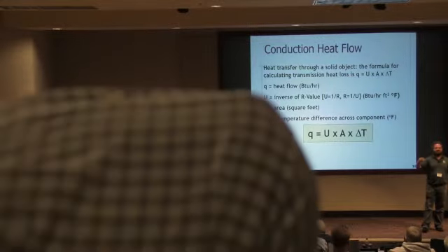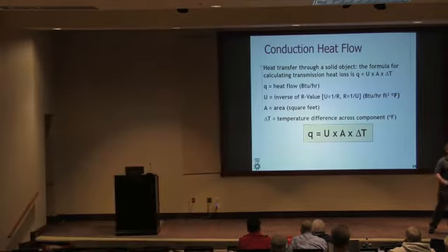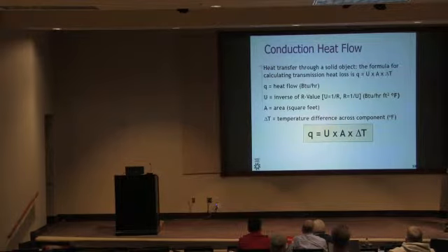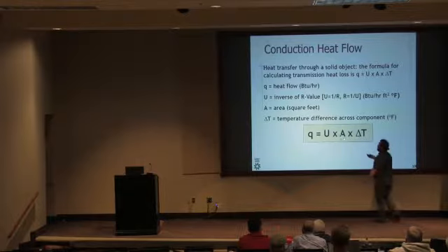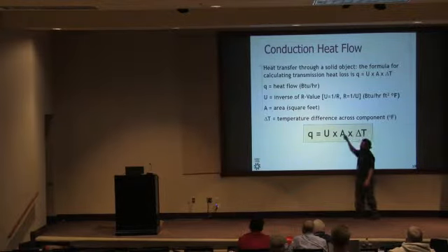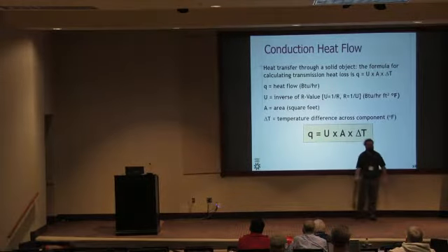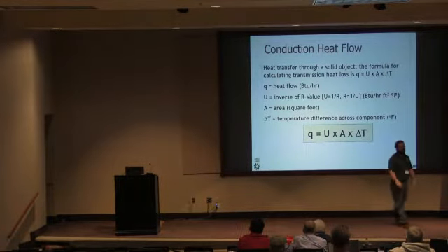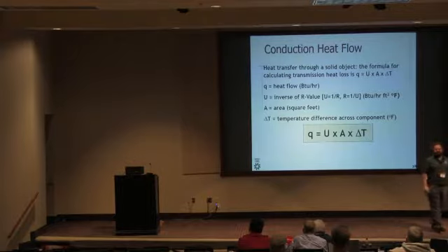It's 70 inside and it's 95 outside. That's a 25 delta T. It's 70 inside and it's 40 outside. That's a 30-degree delta T. How much area, surface area, is experiencing this delta T? And then what is my, basically, conduction across that plane? So Q equals UA delta T is the equation for heat flow that we use in the building science world.